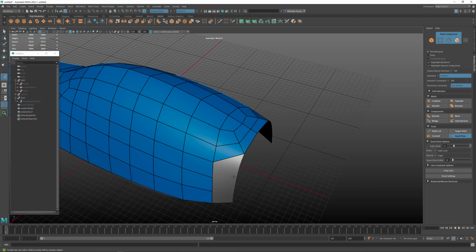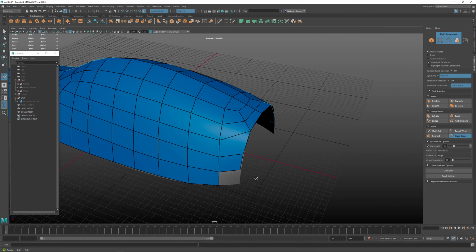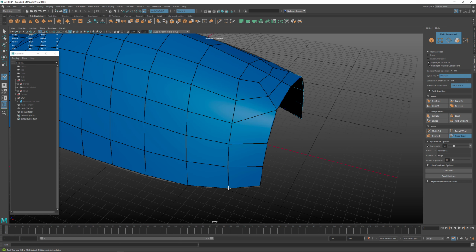Like it can't find it or something, so it's got some kind of issue with line of sight. I can't tell you the exact reasons why it doesn't want to make the geo sometimes, but I've found that sometimes I have to zoom in and take a look at the topology that way. And then like this, I could not grab that vertex. So if I hold down shift, it relaxes the surface a little bit, and you can grab that vert on there.